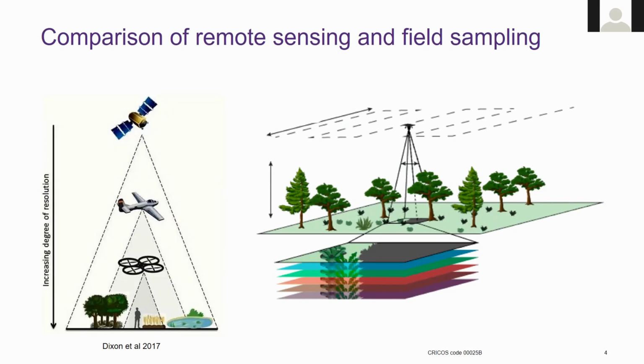Now, drones are different from aircraft, or they're similar, but you're generally collecting imagery or data below 120 meters in elevation. So you're quite low to the ground, and a lot of UAVs can be relatively fast through the air, or you can have them stop to take imagery. On the right-hand side of that image, there's a grid pattern that is flown above a target destination, and images are taken generally, if you want a canopy model or a digital surface model, with very high overlap.